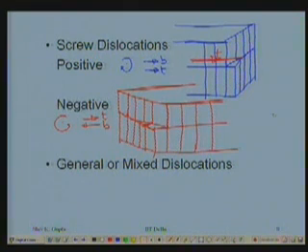And so on, so it will go. So that's the negative screw arrangement, and that's the positive screw arrangement. And of course, as we said earlier, the dislocation line is here. You can take the T vector going in and then draw the Burgers circuit to get this.